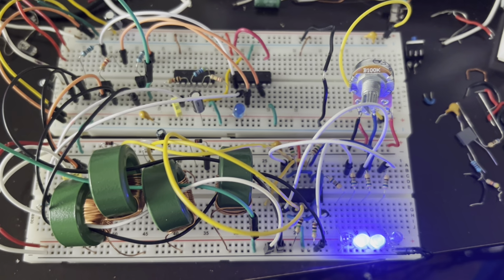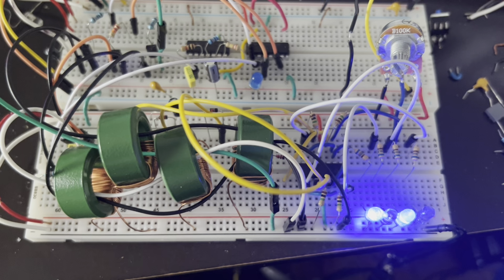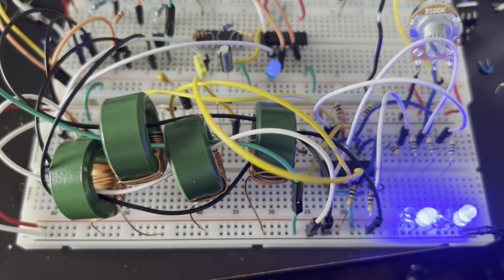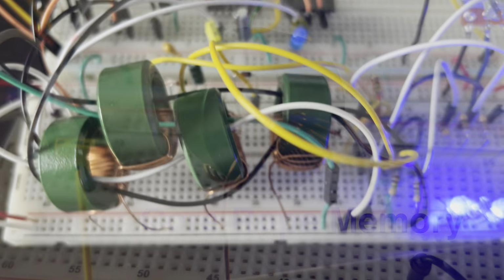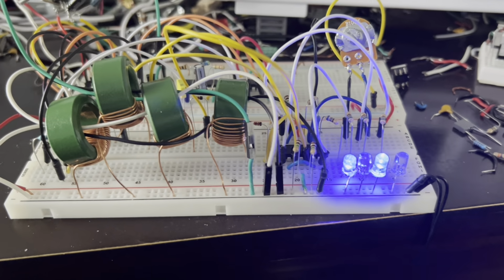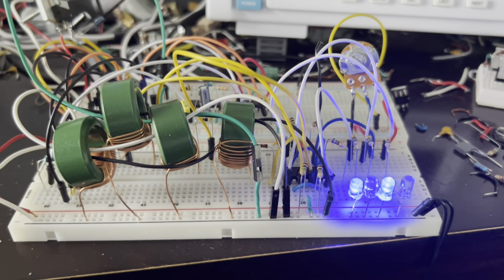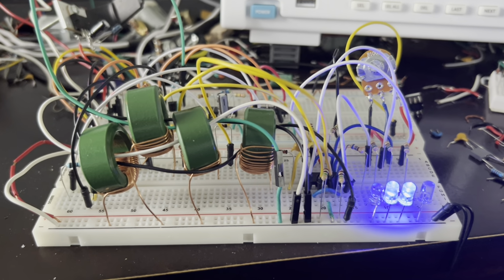So in my last video, I made this 4-bit core rope memory circuit. This is a form of ROM that uses ferrite cores with copper wire that's wound, in this case, 20 times around it, and a high-frequency AC signal is passed through it to ground in order to induce an electric signal in the copper wire.